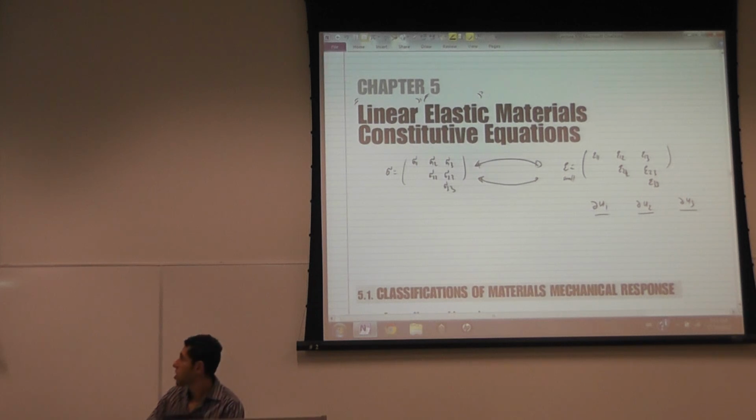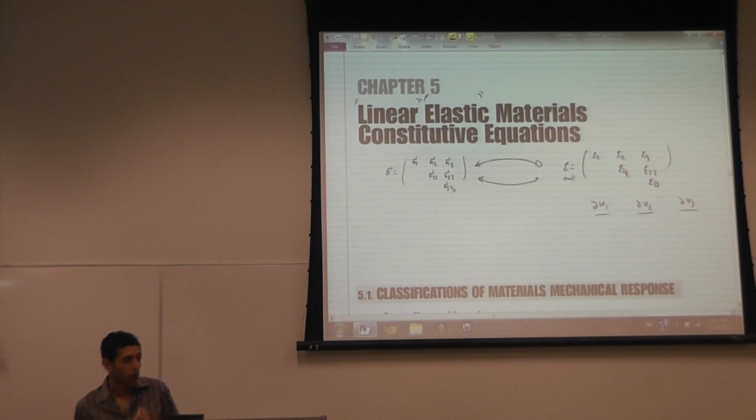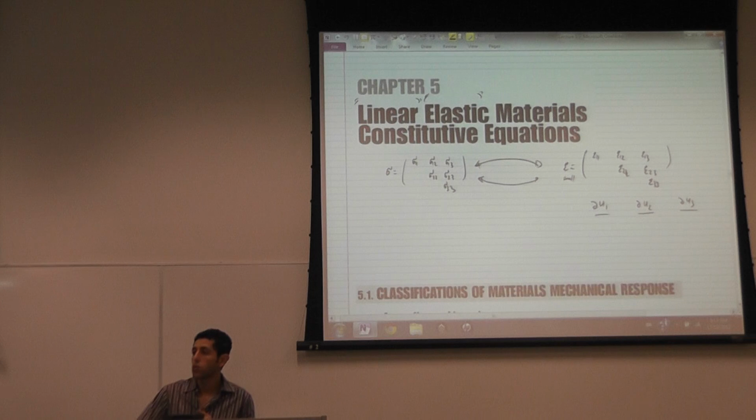And because the strains are functions of U1, U2, U3, I can actually solve the differential equation in terms of U1, U2, U3. Most finite element analysis procedures solve the differential equation after replacing the stresses with the strains. When you replace the stresses with the strains, you write the strains in terms of U1, U2, and U3, and your unknown becomes the displacement rather than the stresses.